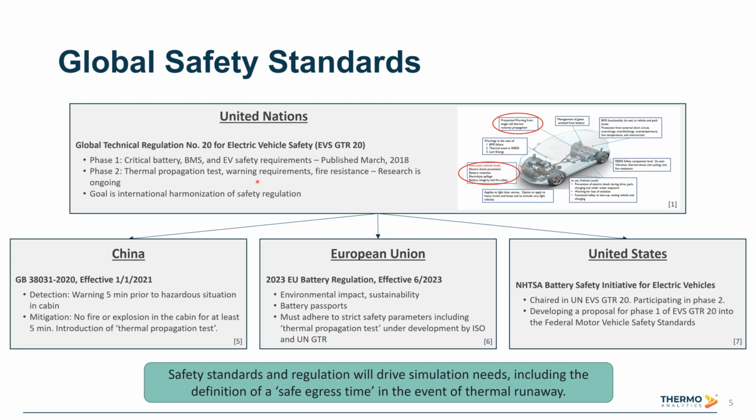So nations are conducting research and discussing research about optimal testing parameters and safety criteria for thermal propagation, fire resistance, warning requirements, etc. China has already adopted their proposed solution for the global technical regulation, which is a 5-minute egress time. So essentially requiring a delivery of a warning to the occupants at least 5 minutes prior to a hazardous situation in the cabin. Of course, this also means no fire or explosion within the cabin for at least 5 minutes. And importantly for us, a so-called thermal propagation test, among others, was introduced. So this is just to ensure that these safety criteria are being met during development.